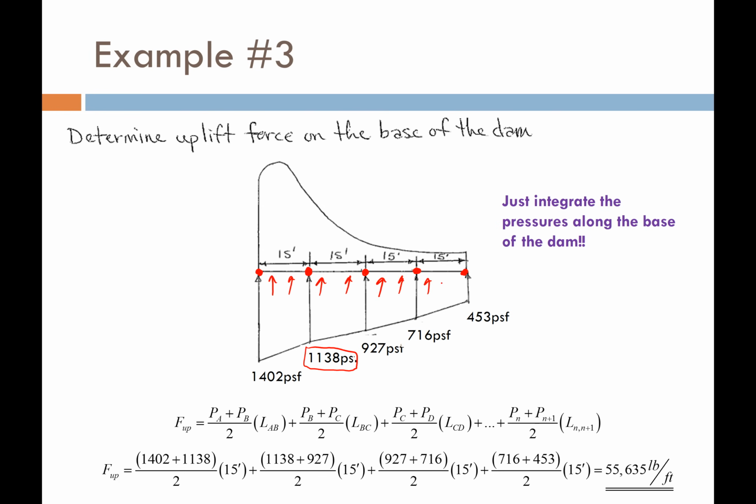If it uplifts the dam, then the water behind the dam might actually push the dam downstream and cause a massive failure. That would be a huge engineering disaster, and we want to avoid that. So what we're going to do is compute the uplift force on the base of the dam. And remember that force simply equals the integral of the pressure.